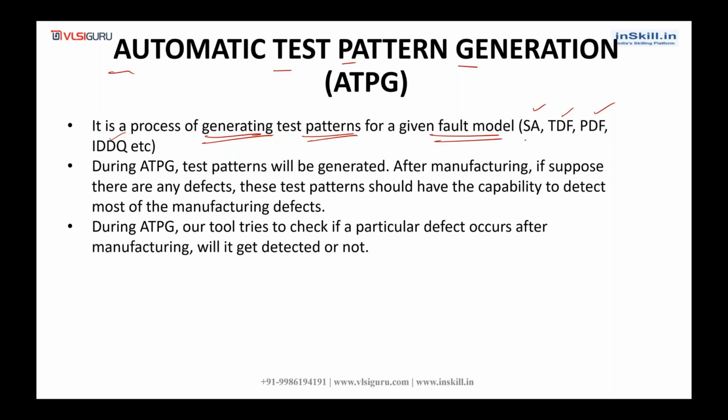So during ATPG, as its name suggests, test patterns will be generated. After manufacturing, if there are any manufacturing defects, these test patterns should have the capability to detect most of them.